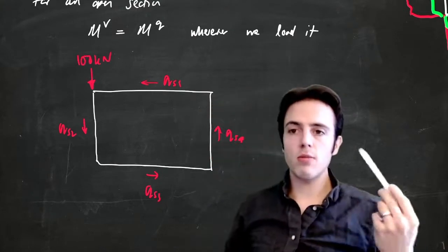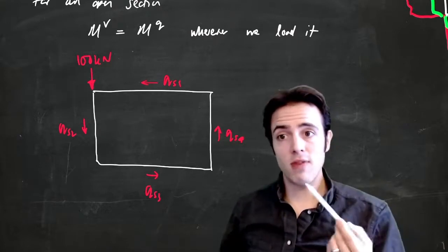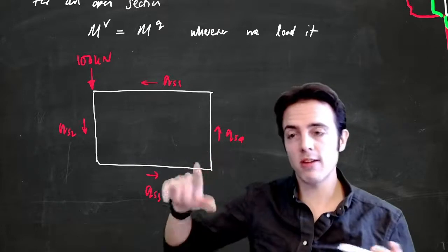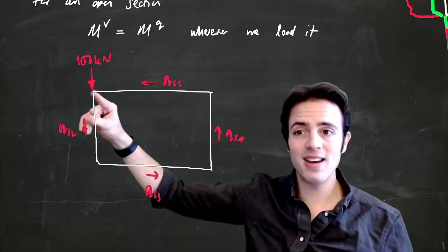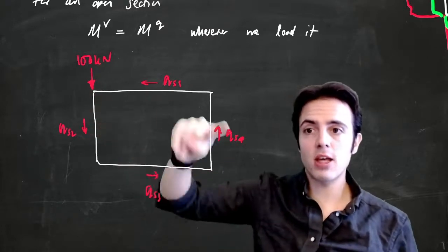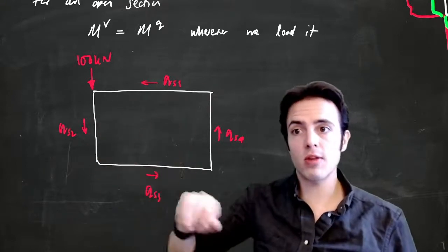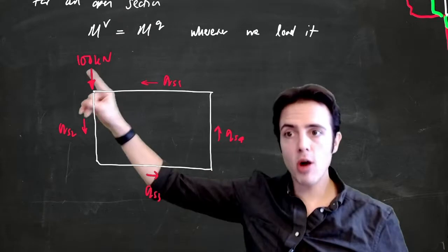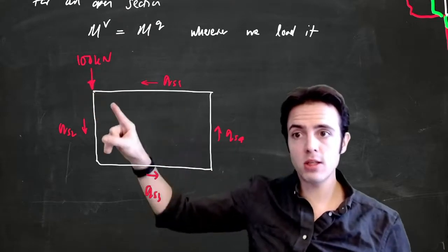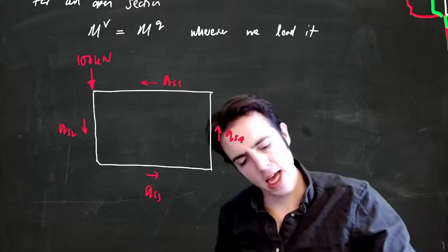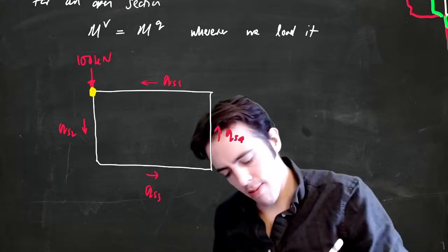So we're going to choose moments about somewhere that we can evaluate them, where this is going to provide a moment, and we can evaluate it with the rest of them. We could also choose to take moments about here, and then we'd have to make Q0 such that the net moment added up to these was equal to 0. But we need to pick somewhere where the moment due to this is equal to the moment due to all of these. So I'm going to, in fact, let's choose to do it here. Let's say take moments here.